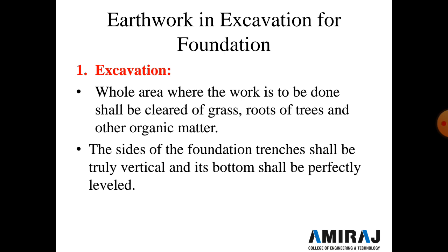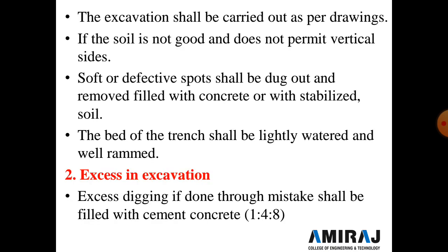So first is excavation. Before the earthwork is started, the whole area where the work is to be done shall be cleared of grass, roots, trees and other organic matter, and the side of the foundation trench shall be truly vertical, and its bottom shall be perfectly leveled. The excavation shall be carried out exactly in accordance with the dimensions shown in the drawing, or such other dimensions as the engineer in charge may decide.